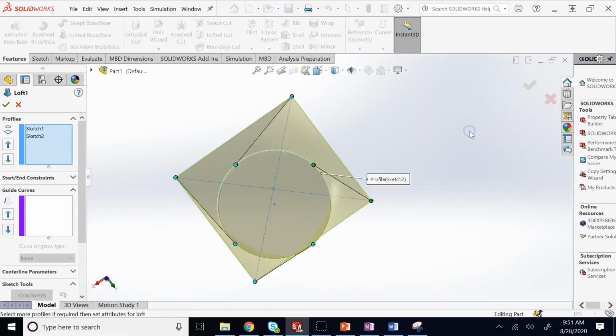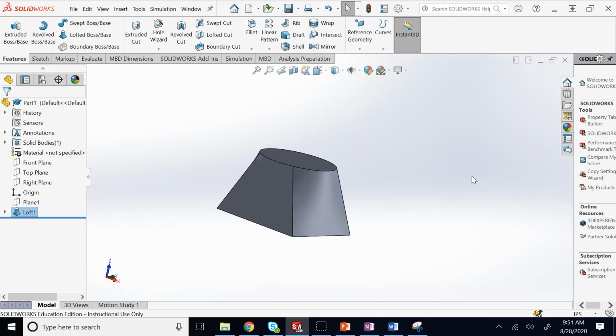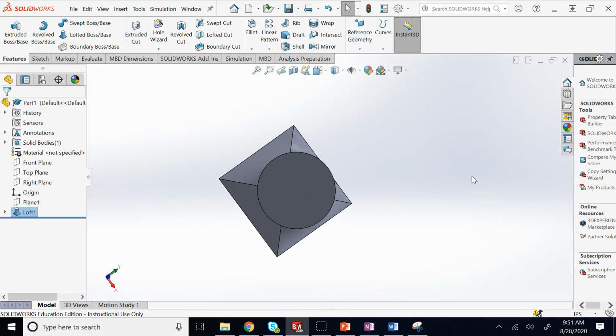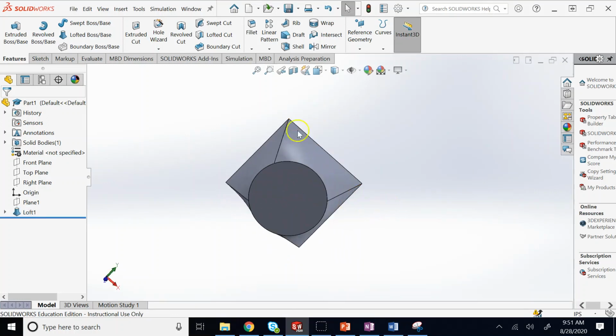So you need to go back, and you can see now here, and you need to make sure that they are properly in front of each other. So this corner point to this diagonal one, this one comes here. Now here it is adding more points for you to figure out, but if you do it properly, then you can get rid of the twist. Okay, so pay attention, that is very important. It still has a little bit of twist on the top, but you can fix that. So by moving the closing points, you can twist or untwist the feature.